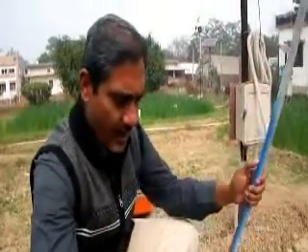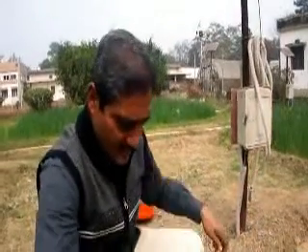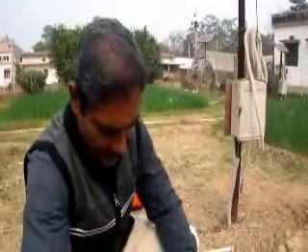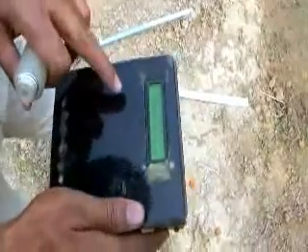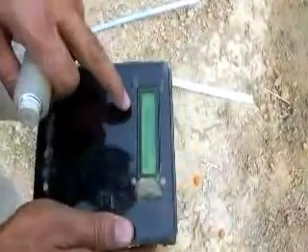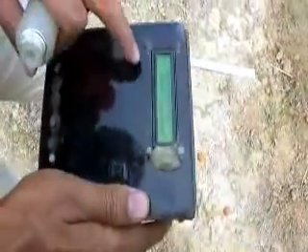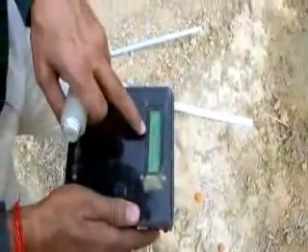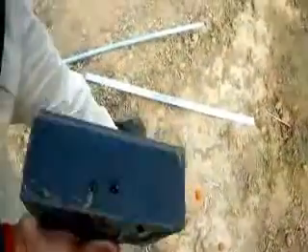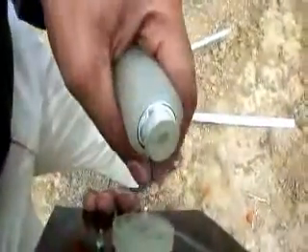So let us see how to read the suction inside the tensiometer. We have a device. To read out the tension or suction pressure created inside this tensiometer because of the hydraulic head or suction of the soil, we have this readout unit which has an opening.